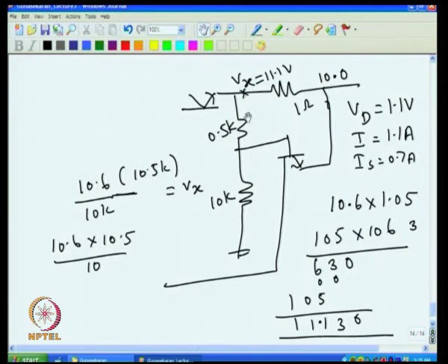So, there is no voltage across this under short circuit condition due to this 10 volt. The net result is, under normal working condition you have this transistor reverse biased, and that reverse bias disappears the moment you short circuit. So, it limits at a much lower current. That is the crux of the issue if you forget about the mathematics behind this, because if you go by the mathematics, it is very difficult to design the circuit.